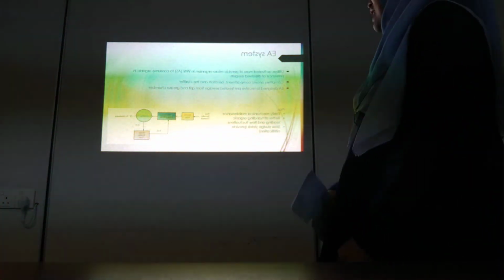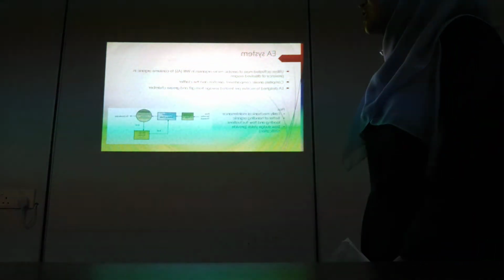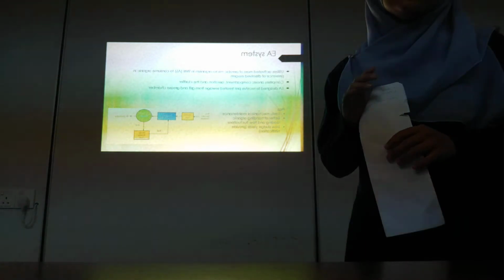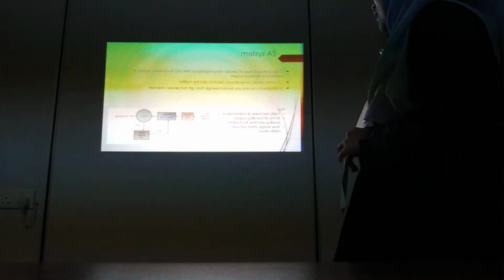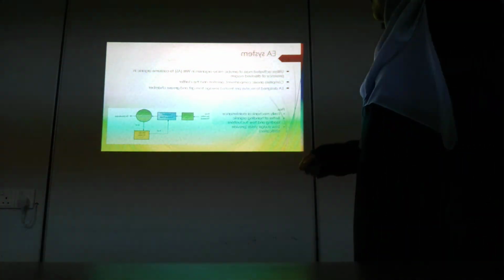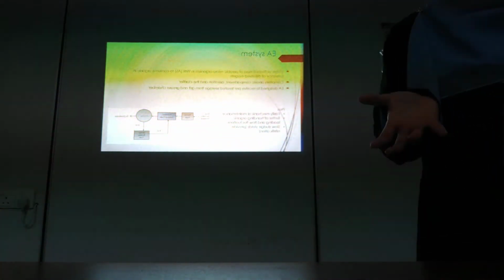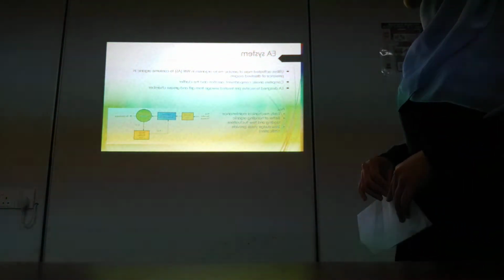The EA system is a system that utilizes an activated mass of aerobic microorganisms in wastewater, also known as activated sludge, to consume organics in the presence of dissolved oxygen. It comprises an equalization compartment, aeration, and clarifier, and is designed to receive pre-treated sewage from the grit and grease chamber. Many people use the EA system because it is easy to maintain mechanically, better at handling organic loading and flow fluctuation, and has low sludge yield, which provides nitrification.